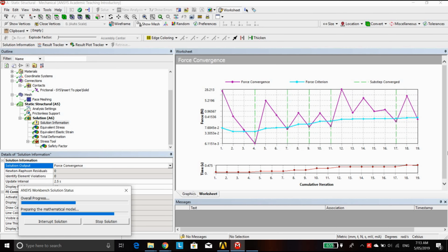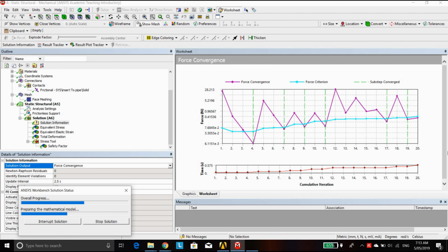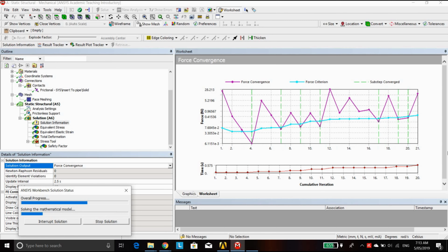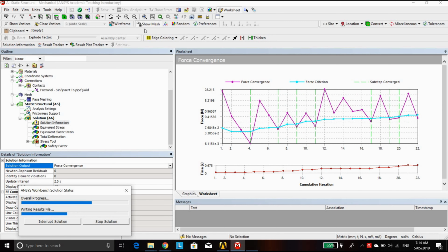There are occasions ANSYS tries very hard, but can't converge. After a while, it is going to tell you, I can't converge, change something, improve the mesh, or the time steps, the sub steps, should be smaller, and you need to edit to help ANSYS to be able to converge. Up to now, 0.6 second simulation is ready.